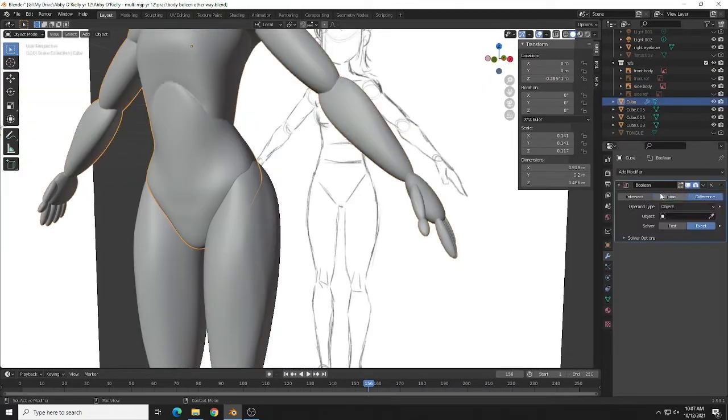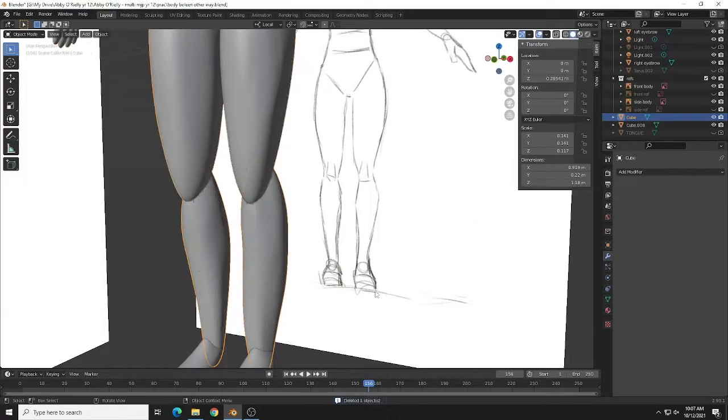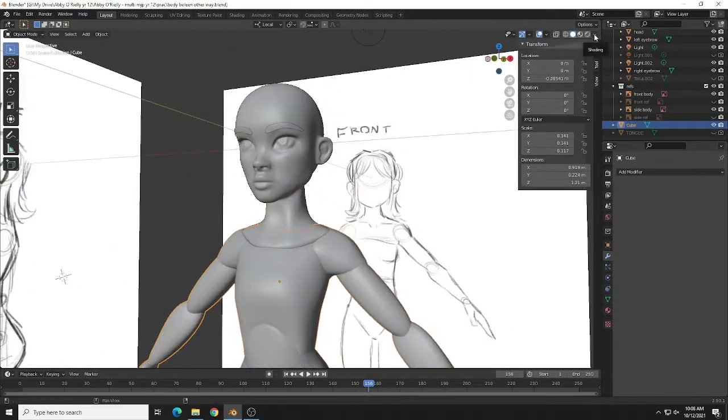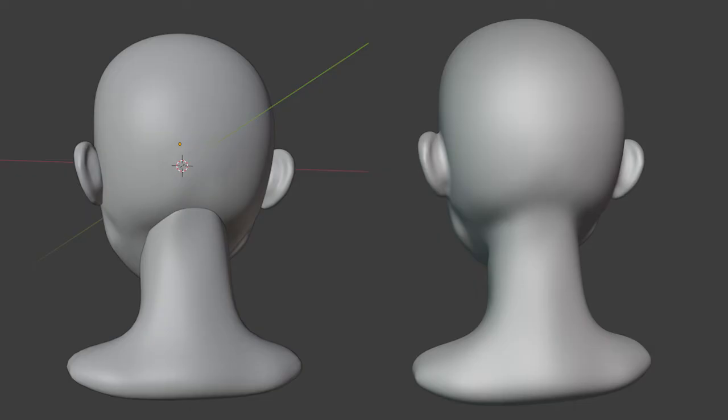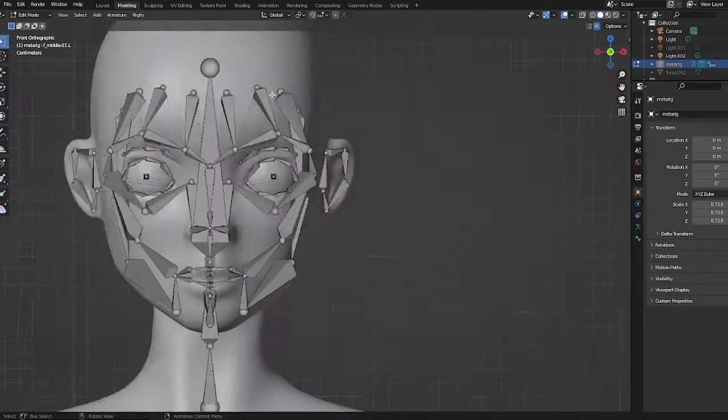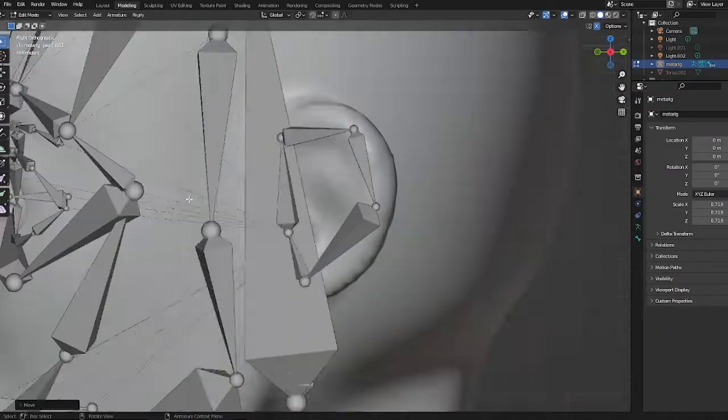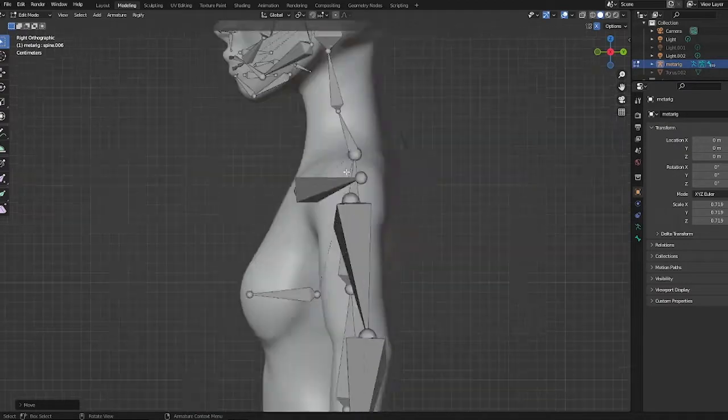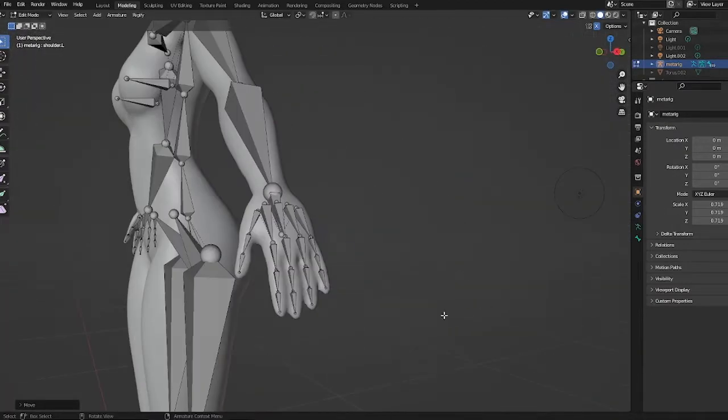At this stage, the mesh can deform, which was resolved by remeshing the model at a voxel size of 0.002, and then smoothing out the indents with the sculpting tools to produce a seamless transition between body parts. Now that the character modeling was completed, an armature rigging system was applied to the mesh. This was done using a complex human meta rig supplied by an add-on called Rigify.